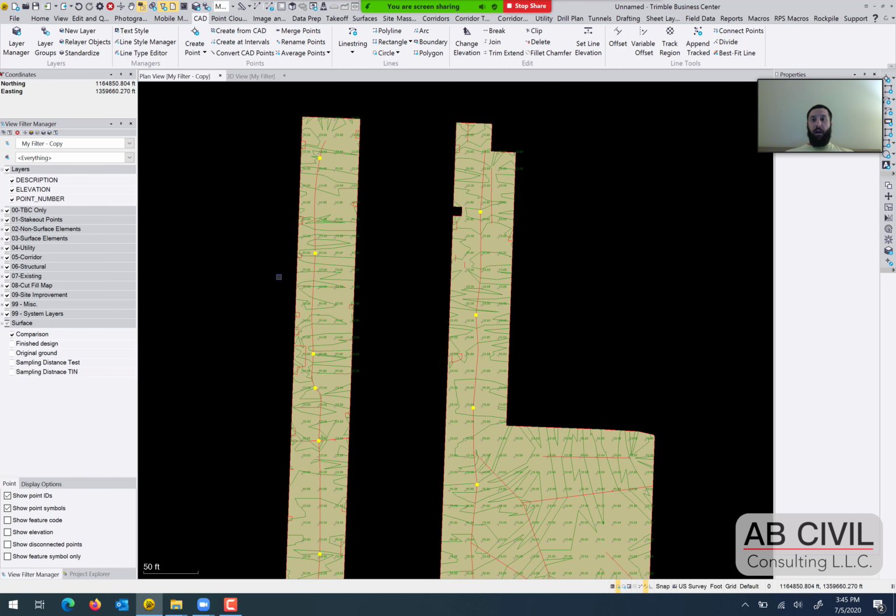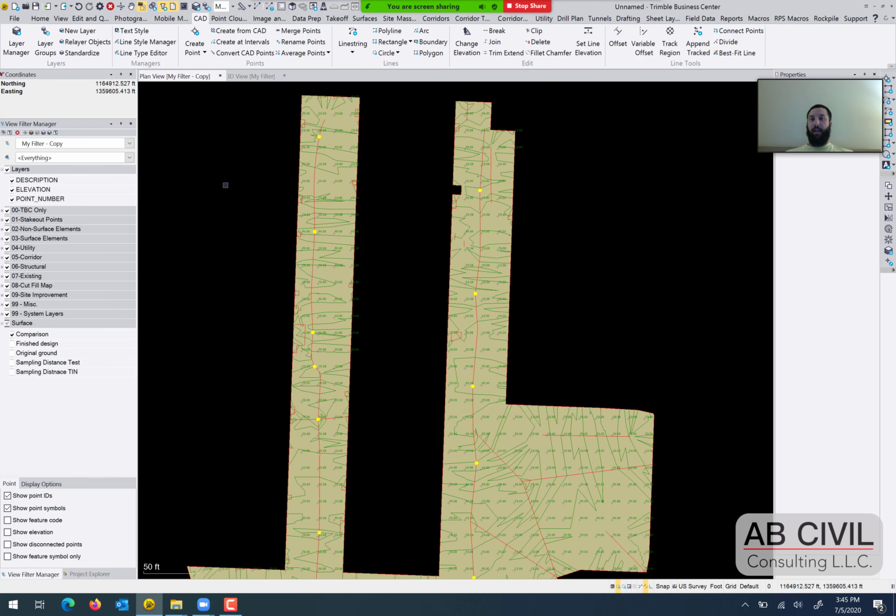Like I said, I saw a couple model builders that hadn't had that setting changed, and maybe they were just waiting till the end of the project before they exported it. But I suggest at least a 15-foot sampling distance when you're building a model. I've changed all my templates right down to 5 feet because sometimes I forget to change it at the end of the project, and it's one less thing for me to forget. So I leave mine right at 5 feet.